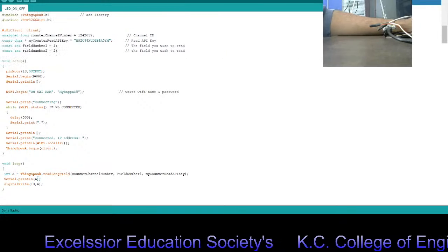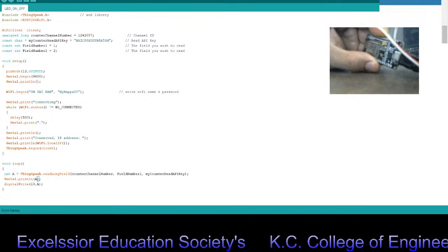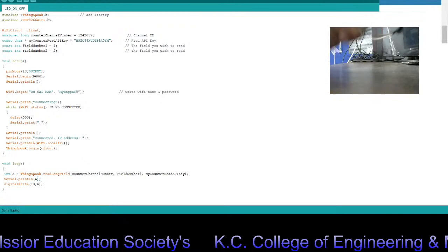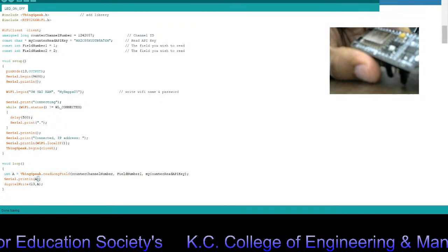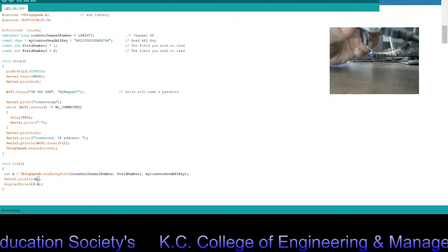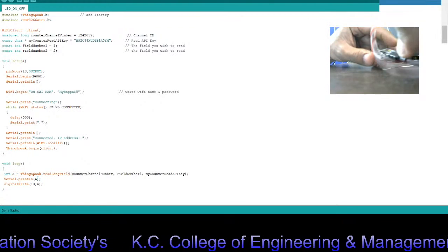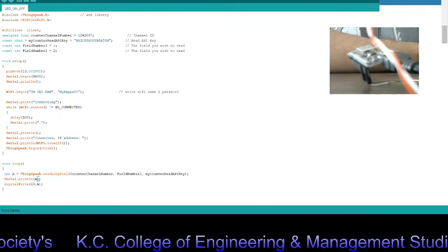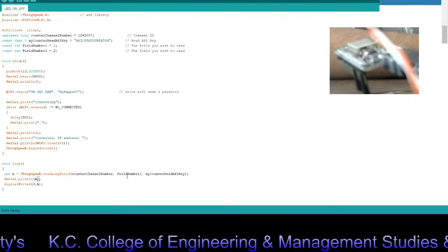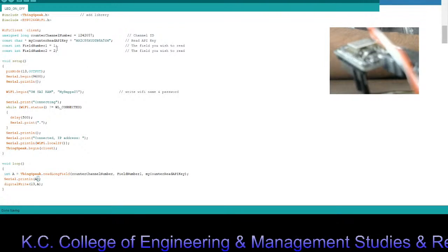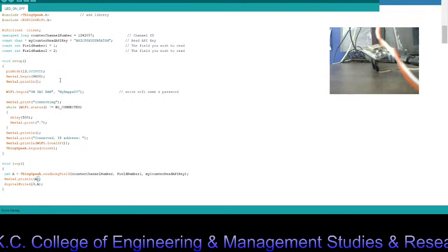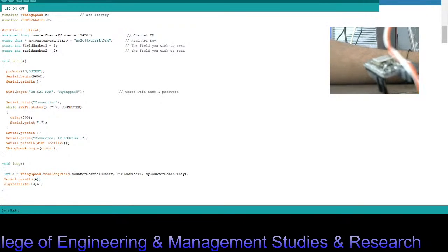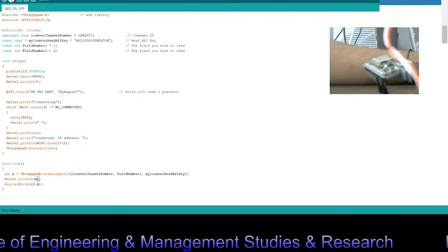So you can see clearly this is my circuit. This circuit I have connected, and that D7 pin is actually very small, so you will get to know. In D7 I have connected one point of the LED and another to GND. So I'll try to glow that LED using the application. So wait, we'll check whether our application is ready. Right now I have written the code. I have connected this circuit to my PC. I'll click on the upload button, which is located in the top left corner.